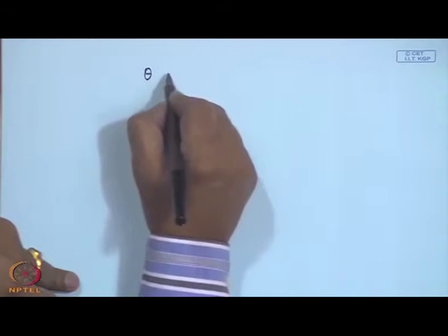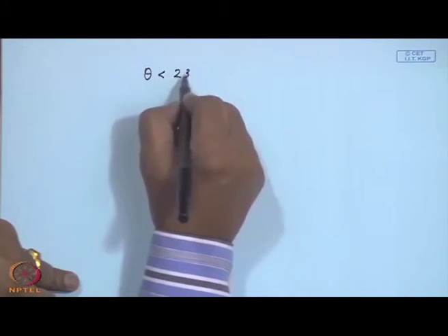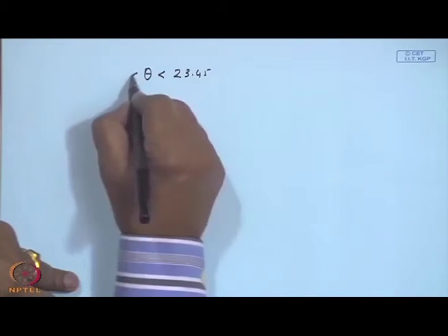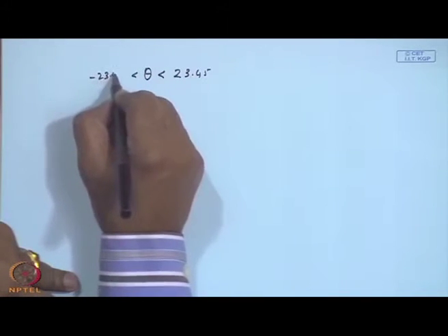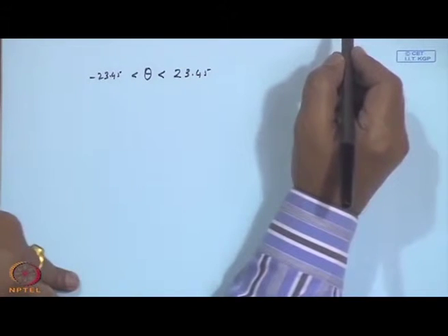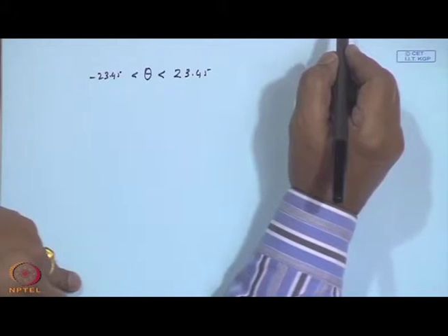The fourth one is the polar mount. It is as if the surface is rotating parallel to the Earth's axis. So, consequently, cosine theta should be equal to cos delta, or theta is equal to delta. So, a word about this: theta will change from plus 23.45 to minus 23.45. In other words, plus or minus really does not matter, because it is cosine theta equal to cos delta.